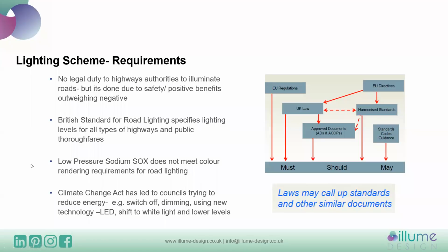Another thing to mention on this one is that in previous guidance relating to bats and lighting, low pressure sodium was often recommended as a light source to use, but it's worth knowing now that low pressure sodium doesn't meet the requirements for road lighting because it has poor colour rendering, which means you cannot make out various colours within a scene. And it's now also being phased out. So these type of lamps will not be available in the not too distant future due to the changes with LED and efficiency.